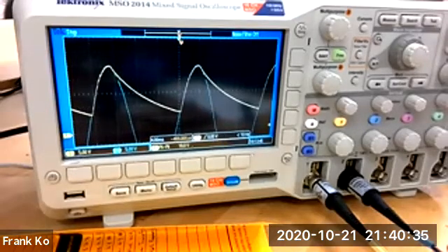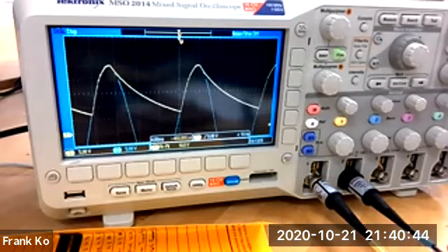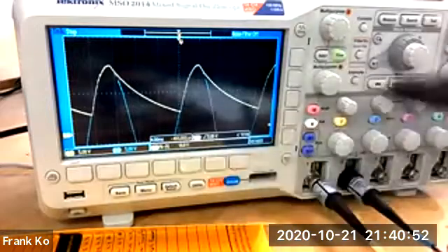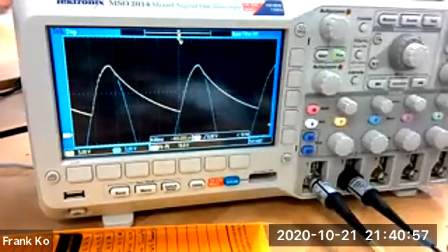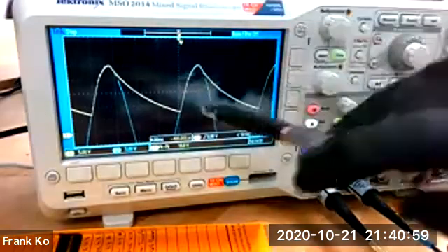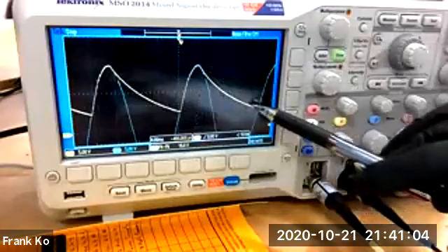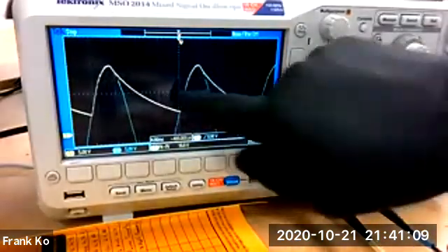So take a look at the change on mine. Look at my screen for a moment, please. This is the image that was frozen by the oscope because I stopped the run mode. This is what I had with the 10 microfarad cap. Going from a 10 microfarad cap, I'm going to put this back in the run mode. You're going to notice the positive peak of the ripple will stay where it is, but you'll see the negative peak will rise up. In other words, I will have less of this sawtooth, we'll have less ripple.